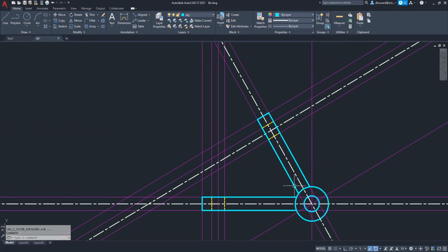It has a webbing on the inside too, so there's no hole in here. This is all solid material. So this gusset plus webbing. The webbing is a thickness of 3/8 inch, and the gusset is also 3/8 thick. So pretty much everything that we're going to do in here and on the outsides is 3/8 of an inch thick.